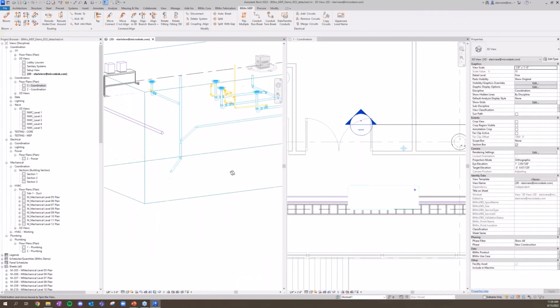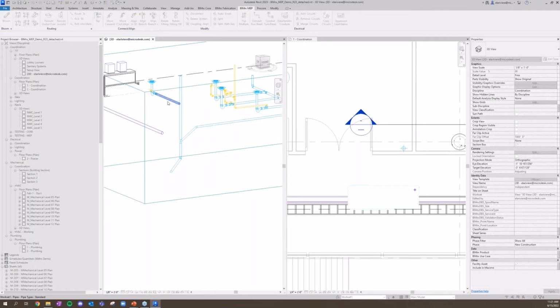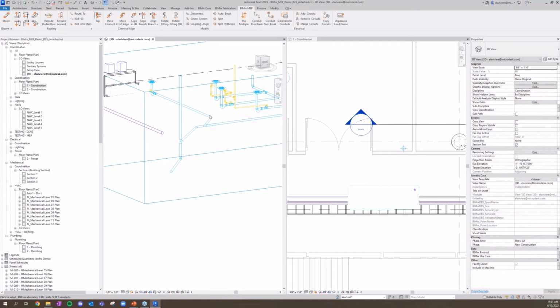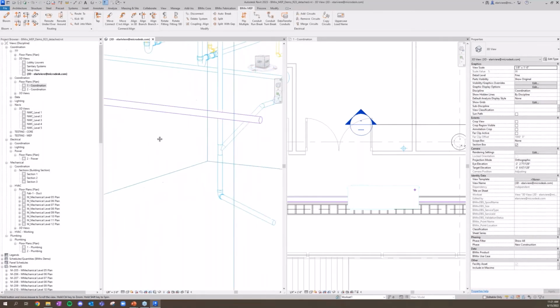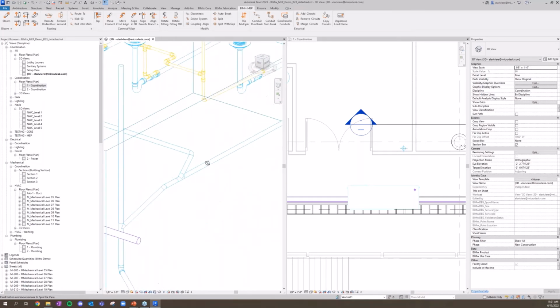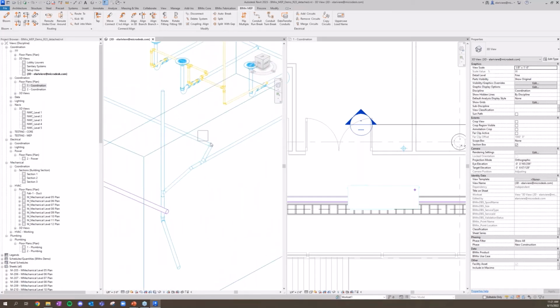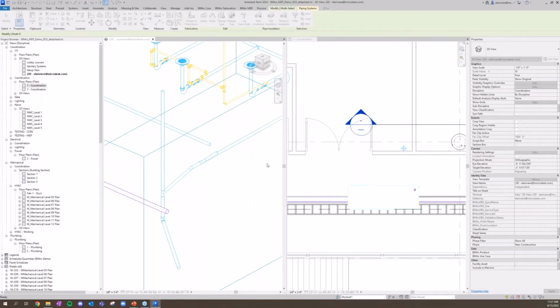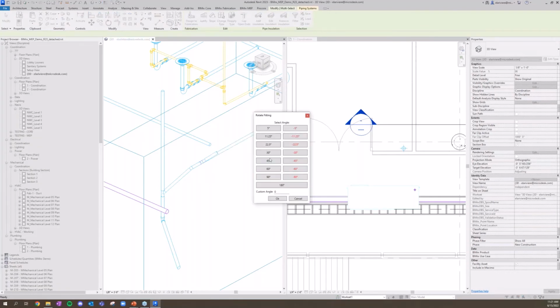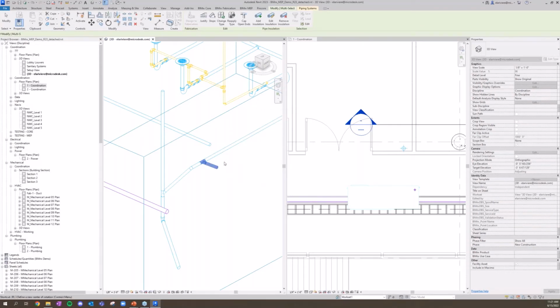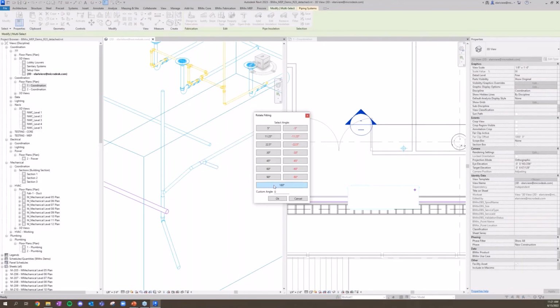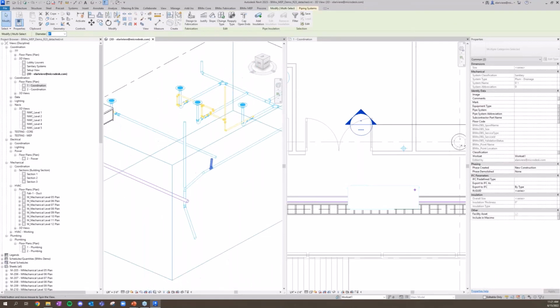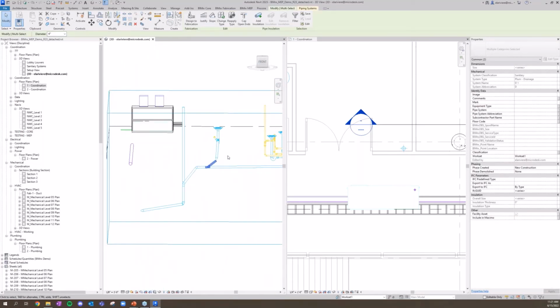And we can see one more really quick auto route, and that is our roll into main, which allows me to choose a main, choose a run, and it 90s in to a 45 connection on the main. And we can very quickly take that exact shape and turn it into some other cool stuff. You can delete the elbow, grab the center portion, rotate fitting 45 degrees. Again, if we hit the wrong one, it's as simple as a 90 or a 180 in the other direction. All right, just keep rotating and eventually you'll get there, right?